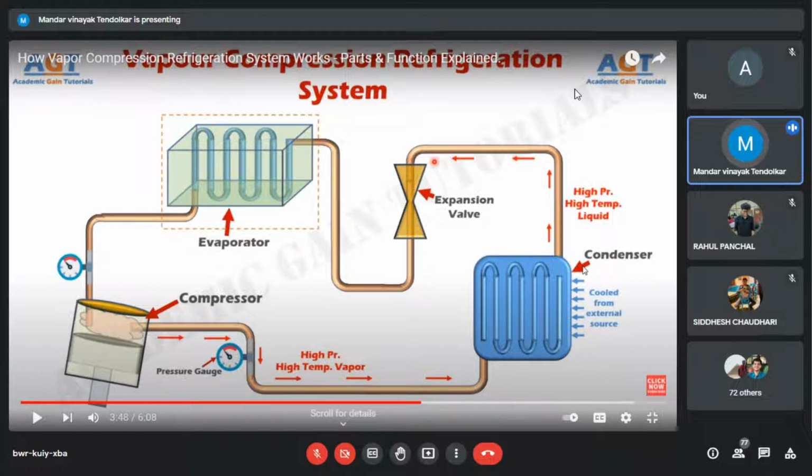Okay, this is a condenser. It has to reject the heat. That is why phase change takes place. So this would be at a slightly lower temperature. What the person is saying is that the pressure is constant and it is just a phase change. So naturally, as the phase change is associated with constant temperature, that is why the person is saying high temperature. But this is not a high temperature as such. There will be slight cooling also. In reality, it is, let's say, superheated vapor. I will say over here high pressure, high temperature means superheated vapor.